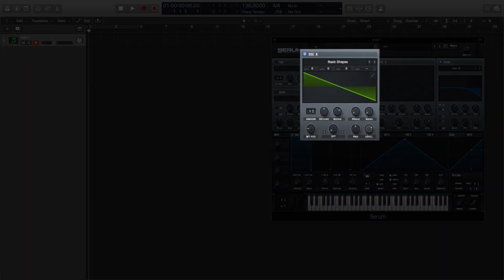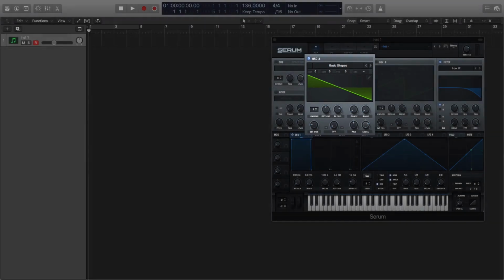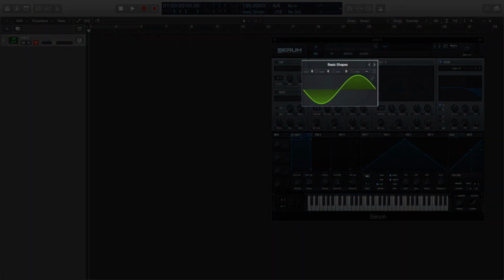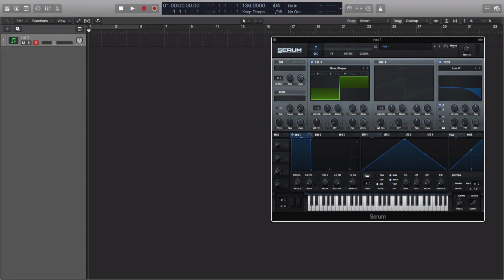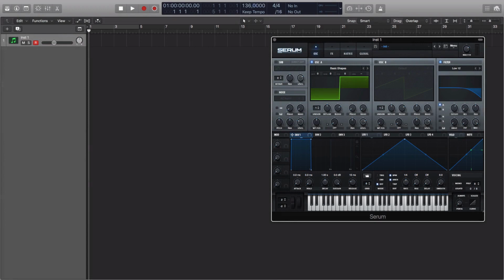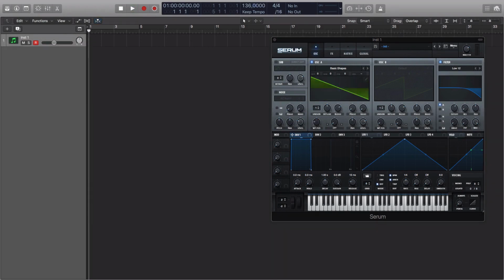The oscillator generates a continuous sound wave, and its main parameters are usually the waveform and pitch, or frequency. The waveform is where we choose the type of signal which is being generated by the oscillator. We usually have the basic waveforms to work with: sine, triangle, saw, square, and we can also have a noise generator. That will dictate the harmonic content and therefore the timbre of our sound.